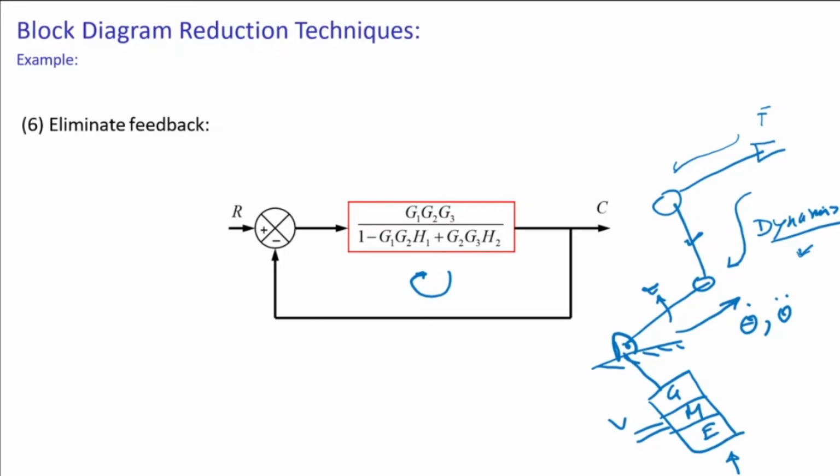Let's look at it here, this will make it very clear that we have a motor, a gear, and an encoder. This link is moving, this link is not moving, it's fixed. But because this link is moving, an effect of that motion will come on this joint also, which the controller has no way of knowing. So this will act as a disturbance on the controller.